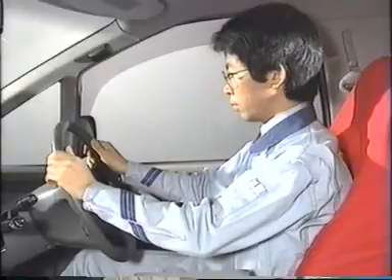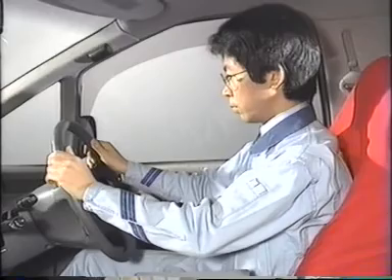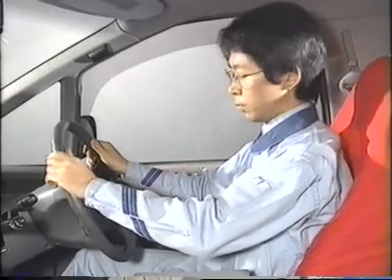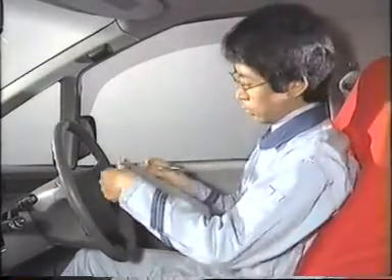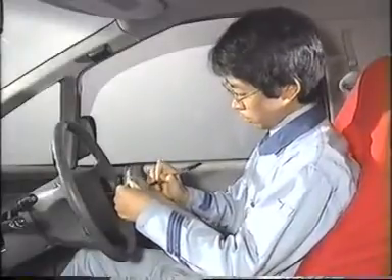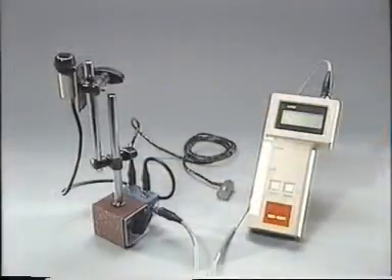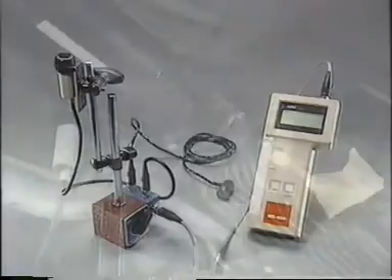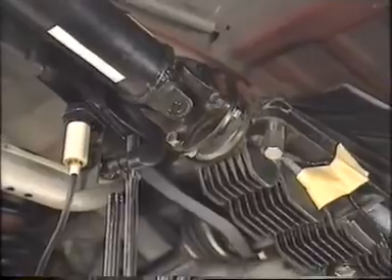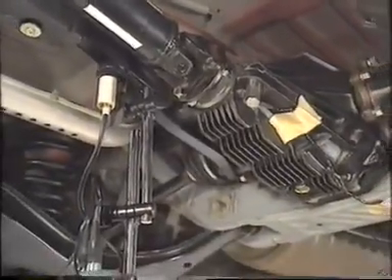The propeller shaft balance may be checked by other methods also. It can be determined by a feeling test as you move a trial weight from one point to another. Or it can be determined using a propeller shaft balancer. You will find more details about this method in the NVH diagnosis manual.